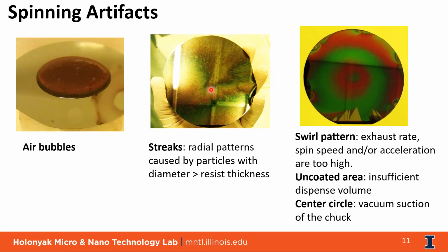All right. And the second major thing that can happen from your photoresist is when you do not use the photoresist for a longer period of time, at the nozzle it can get dried off. Then when you open the bottle, all these dried particles can fall into your photoresist and create particles. So make sure you properly clean your photoresist bottles often. It's free of particles.